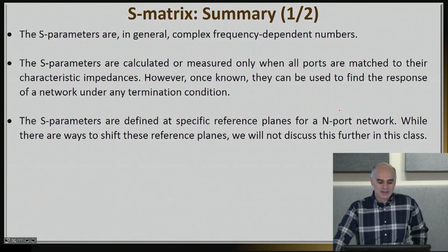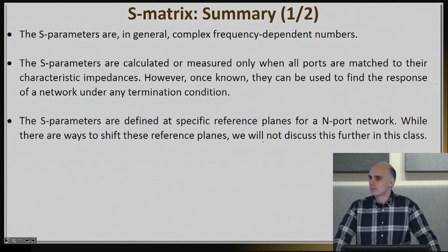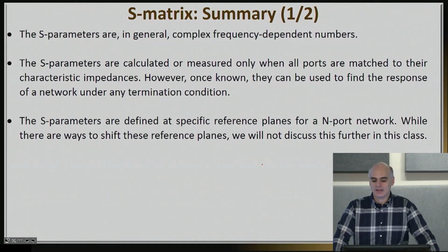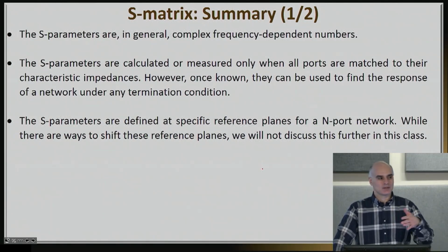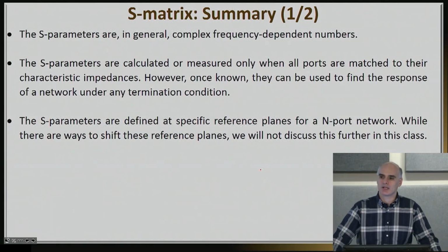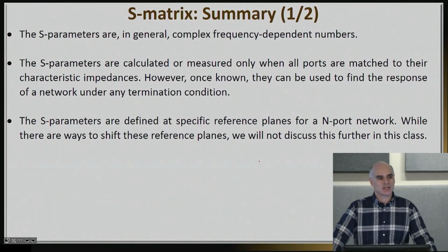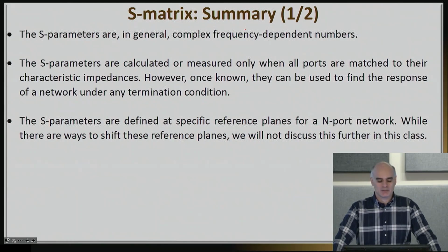The other one is that the S parameters are defined at specific reference points. So that means that if you change the reference points and you move them by a specific length, you have to recalculate the S parameters. Our textbook actually gives you those calculations, and you can find them very easily online. I have not covered them in this course.